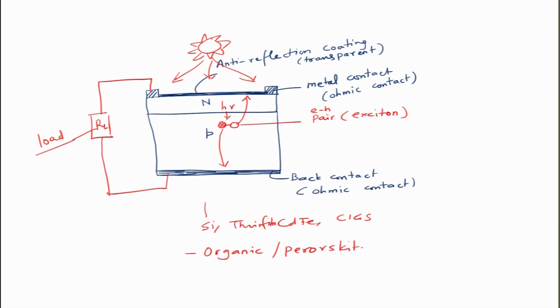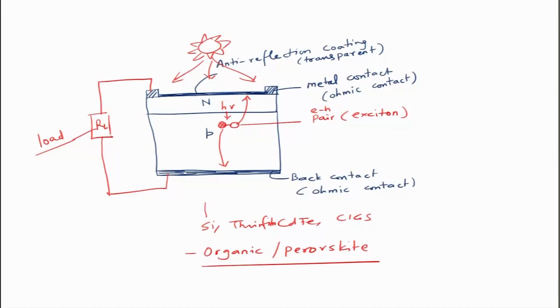In this case, although you have bilayer solar cells also, the typical architecture is where P and N materials are mixed together at microscopic scale, and in between the contacts there are also carrier selective coatings which preferentially allow certain types of carriers to go through, so holes will go preferentially to the anode and electrons will go preferentially to the cathode. So, this is a typical device architecture that we see for a solar cell.